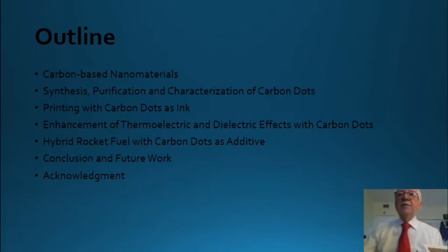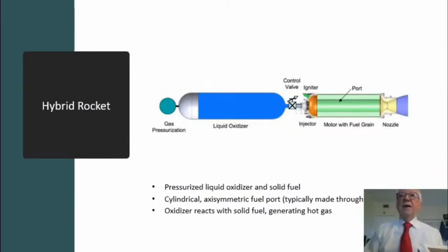Saying that, the way it works is the following. We have a liquid oxidizer, and we have a chamber related to what I call the port. And there is a possibility to inject the liquid into the port for combustion measurements. For the liquid oxidizer, we can use nitrous oxide at room temperature, but at high temperature it's better to use another one, and at low temperature, it's better to use the liquid oxygen. And with this control valve we introduce the liquid oxidizer into the chamber.